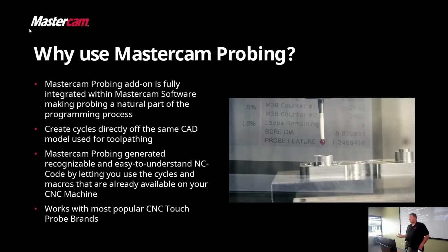So a couple of reasons to use Mastercam probing: we're going to program it directly off the same model that you're using for tool pathing, making the programming of the probe a natural part of the process. That way it's put in as a standard operation. You can run it through any of your simulation options, post out as part of your main file, and now you have a single ready-to-go file for the shop floor.